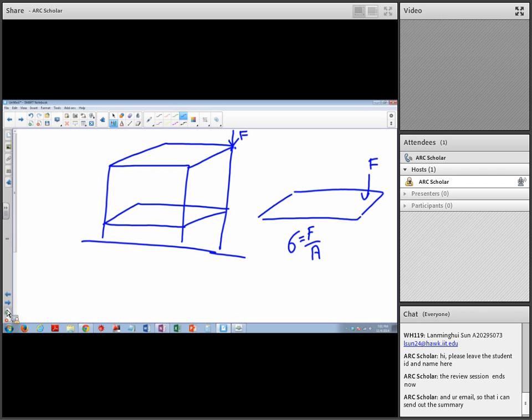So let's say this is the box, right? If you are pointing this way, here we have a tension right here, and at this edge we have the compression. So if the question is asking you for the stress at this point, you use F over A minus My over I. F over A is plus, I'm sorry, it's plus, because this is coming downward and because of compression, this is coming downward. But for here it is minus because one is coming downward and one is going upward.